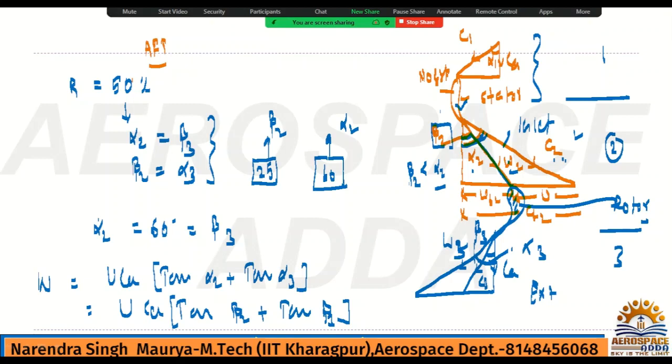After hitting, only then will it start rotating. So when the rotor was stationary and the flow is coming with very high speed, at that time the relative velocity will be very high. So before the rotor the relative velocity will be less, but after the rotor the relative velocity will be increased. Similarly, before entering the rotor the absolute velocity will be high, but once it passes over the rotor blade, the absolute velocity will be decreasing. That kinetic energy will be decreasing because it is hitting the rotor, so the energy will be absorbed by the rotor, used to do work on the rotor, and then only the turbine will start rotating.